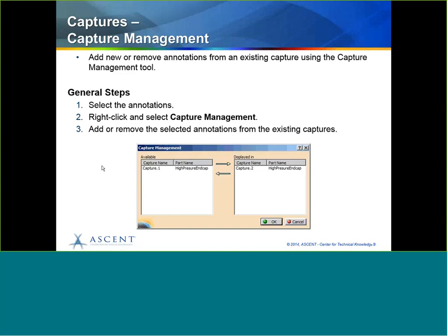Now, once I've created some captures, I may discover down the road that there are annotations that I want to add or remove from my capture. You simply select the annotation, right-click, select Capture Management, and here you can either push annotations into your capture or remove them from your capture.